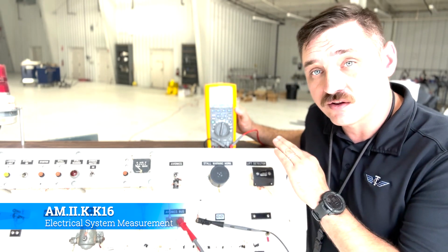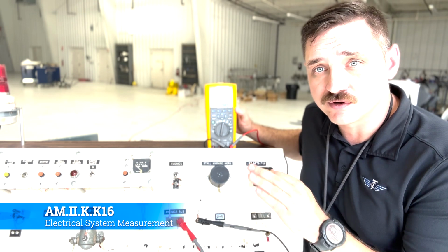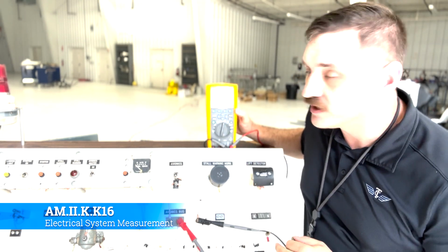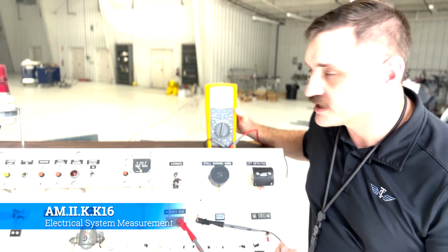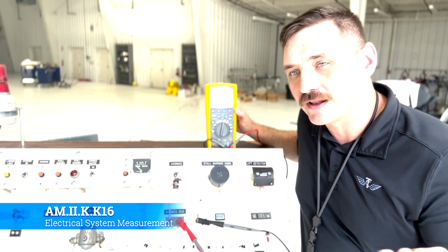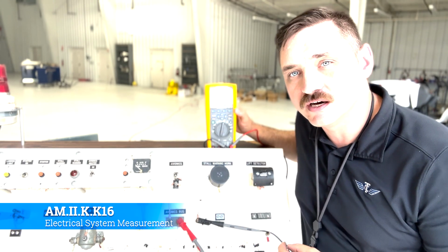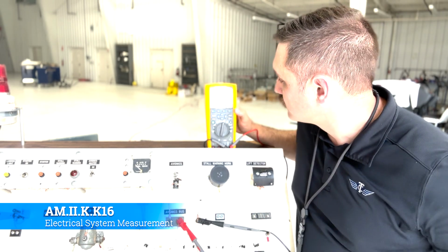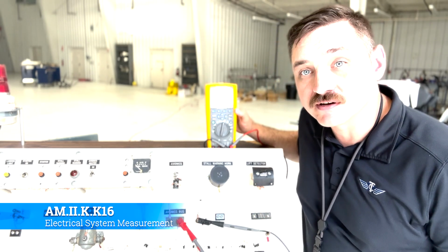And we notice that all of a sudden we have no continuity. If you can see that from where you're at, we'll turn the alarm on. It's saying that it's an open line, that there's no continuity on there. We put it back, all of a sudden we get something.